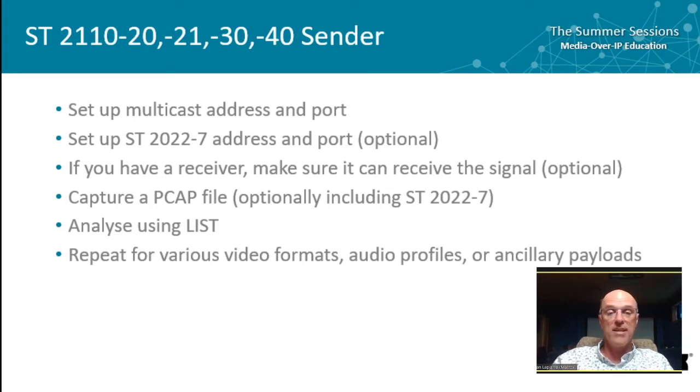So maybe you're doing a test for a sender in 1080i, but also in 1080p or UHD. For different audio profiles, you can have stereo, you can have 16 channels of audio. So repeat the test for these different things and for different ancillary data payloads.